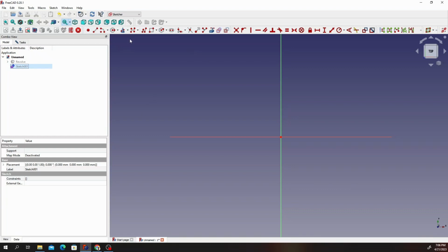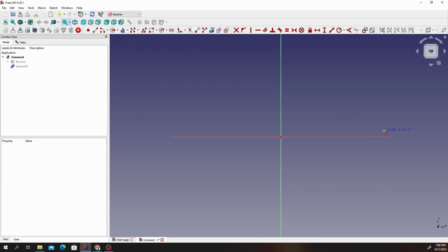And we are going to click on the polyline, and we're going to start our outline again. So make sure these lines are straight like that. Make sure they're completely straight like that. Like that. Like that. And make sure it clicks constrained and click there like that. Okay. Once we have sketched that, we are going to go to constraints again.